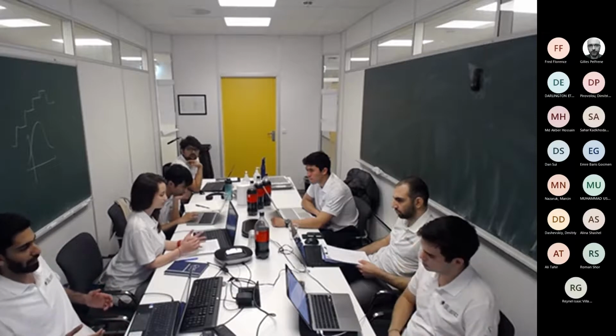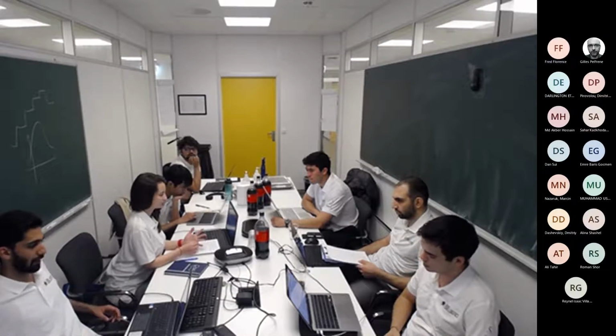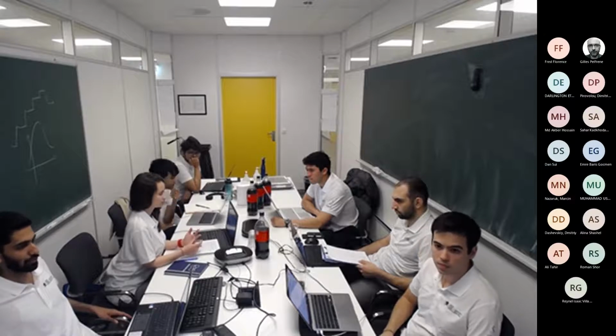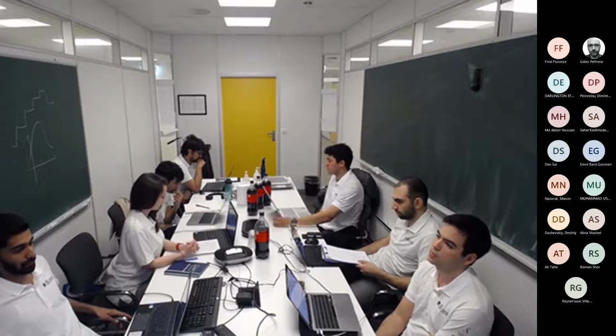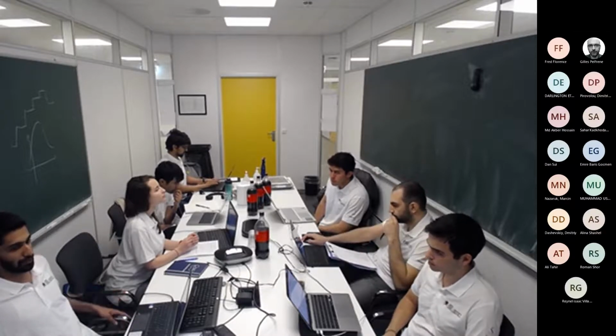In this master's thesis, the training environment is based upon the OpenLab simulator that is developed by NORCE, and the agent, which is a PPO agent, tries to find a policy with which it can maximize its reward. When I say reward, it means that the most stable response with the least overshoot and the least oscillations will give the maximum reward for the case of MPD. And obviously the best suggestion for the reference bottom hole pressure, which is supposed to be kept near the pore pressure to increase the ROP.